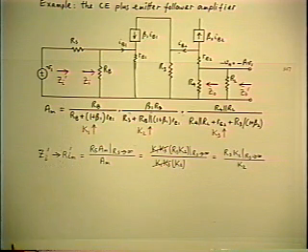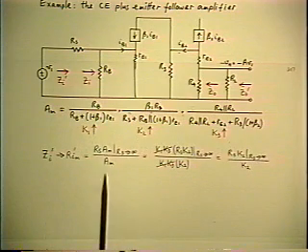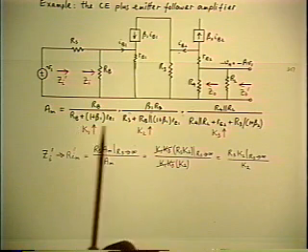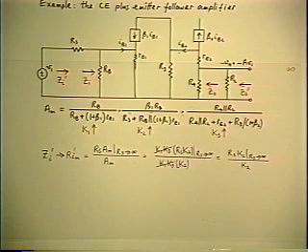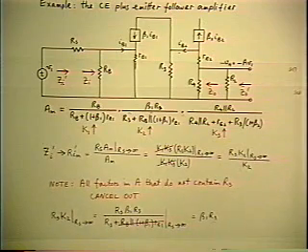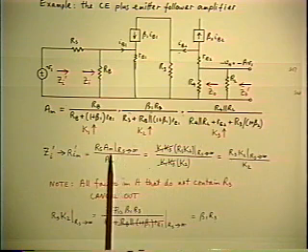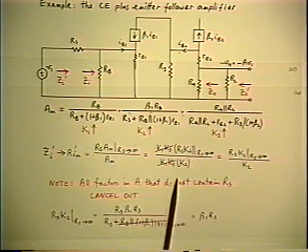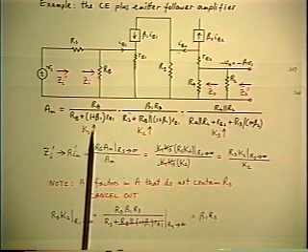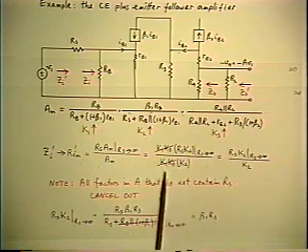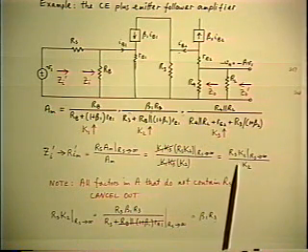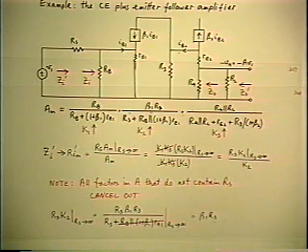Mid-band input resistance. The theorem says we substitute for the AM both numerator and denominator as K1, K2, K3. The same giant simplification. Any of those factors that doesn't contain RS cancels out because it's unaffected by the limit. K1 doesn't have RS in it. K3 doesn't have RS in it. They go away. K2 does have RS in it. So it stays. And that's all you have to work on.